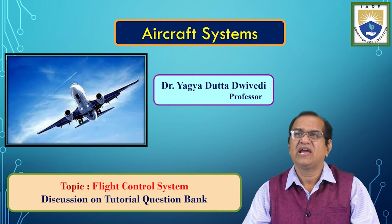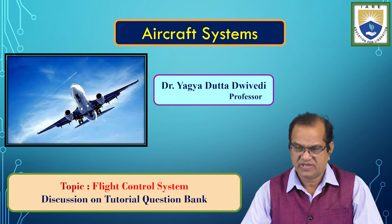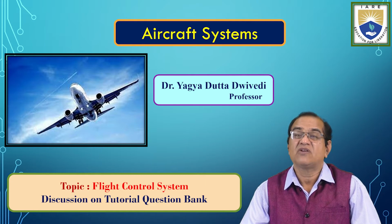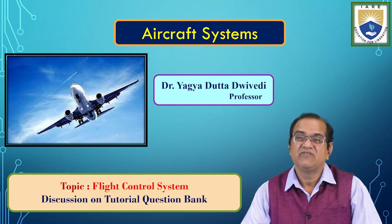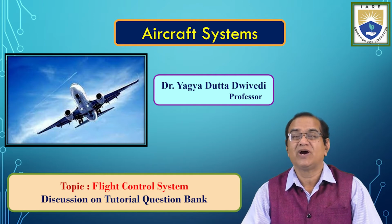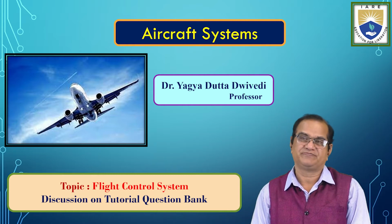So these things were covered in module 1. In module 2, we have seen the aircraft electrical system: power generation, power production, power control, safety, and conversion, and different types of power, AC and DC. In AC, we have the constant frequency and the variable frequency, 115 volt 3-phase. If you talk about the DC, we have the 28 volt DC, then we have 270 volt DC. These 4 types of power generation are used in aircraft.